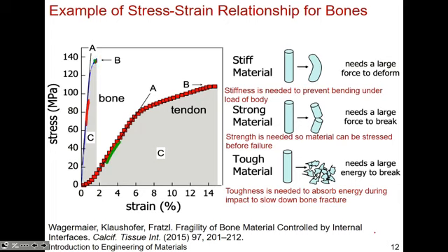And then we could also think about the strength. Okay, so I've talked about strength here. If we do the 0.2, let's see, 0.2% is somewhere near here. So if we were able to zoom in, I'm not drawing over the line, it's just 0.2% is very close to the line itself. Let's say we draw the 0.2%, then this would be the yield strength. That would be the definition of when your material stops being elastic and starts experiencing plastic deformation, okay?